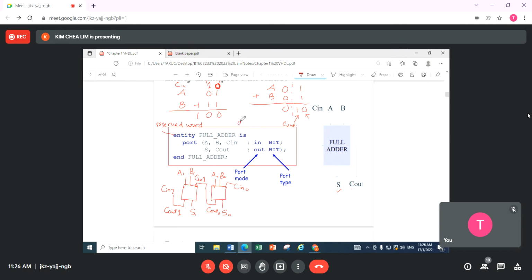In fact, if you type in the AND, it will change color already. You will see this when you're doing your practical. This AND is a logic AND, not your English 'and'. So these are all the reserved words, in the sense that when you type, they have a special meaning in VHDL. And in Quartus II, the software that we are going to learn, they have a color, if I'm not mistaken, red color.